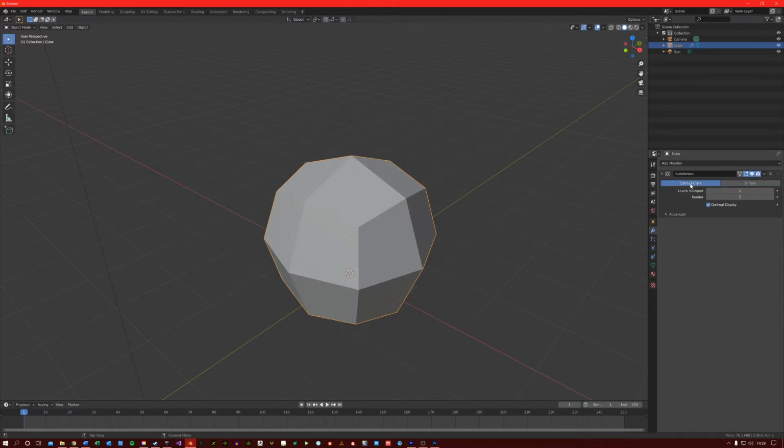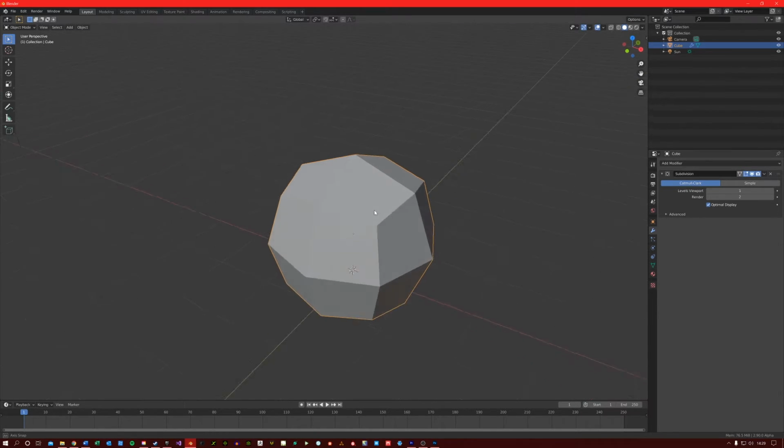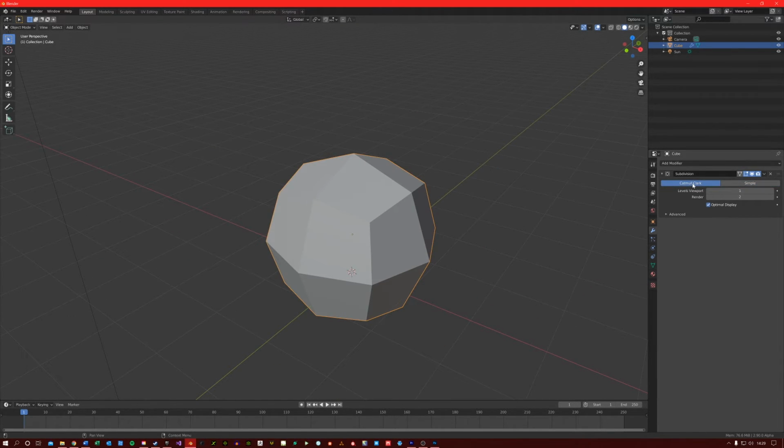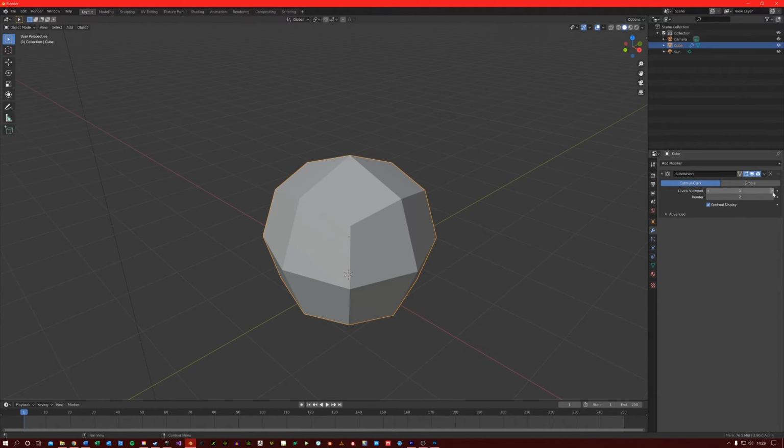So we know that the simple mode retains the shape of the mesh and adds more density, but what is the Catmull-Clark mode? The Catmull-Clark mode is a subdivision algorithm that is used to create smooth surfaces, so it is essentially smoothing out the corners of our mesh. I will put a link in the description of this video if you want to read up on this algorithm a bit more. If I keep subdividing this mesh, you'll see that our cube eventually becomes a sphere.